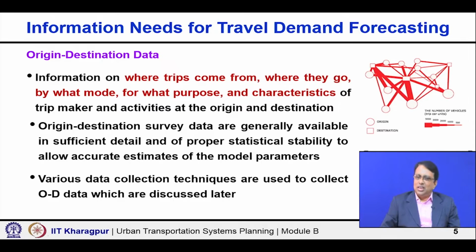Various data collection techniques are used to get the OD data in sufficient detail, and we use it for multiple purposes, basically to estimate the model parameters. As I said, this is very important, because in the base year you need to know the dependent and independent variables both, then you can develop the relationship. Model building is all about capturing the relationship. So, we need independent and dependent variables both.